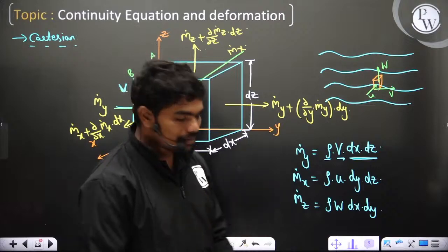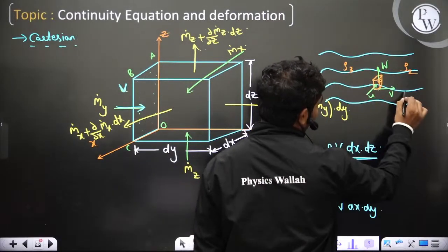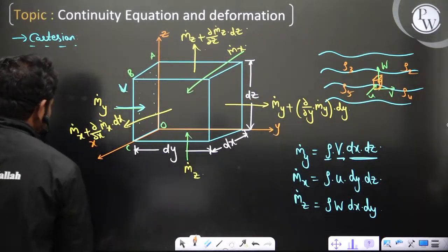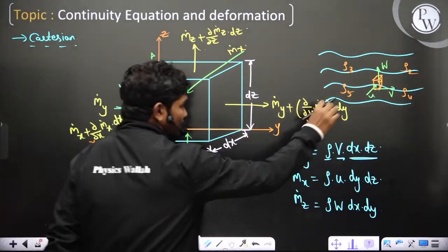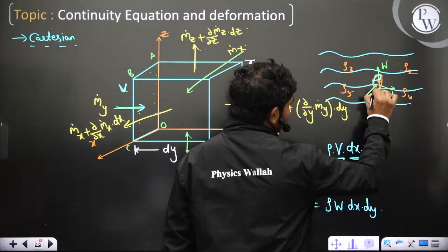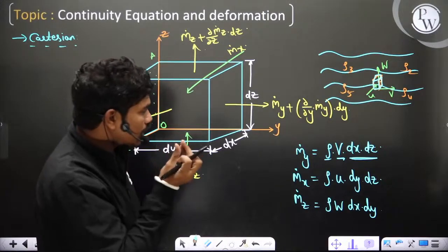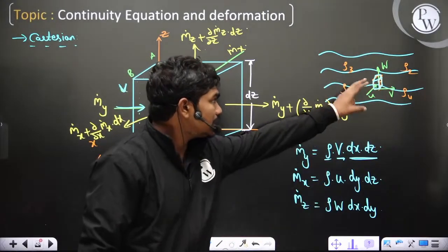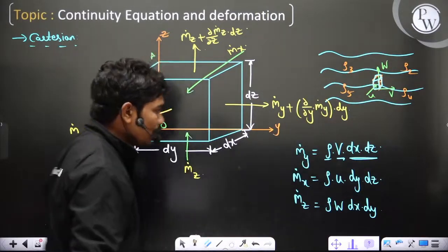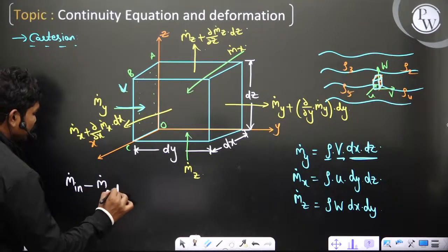Okay, now the main important point is this density may change from location to location, because the flow need not be incompressible. So it can change from location to location. Now you can see in this element, because practically this fluid element is of some fixed mass, if you take this small volume whatever you have here, then in that small elemental or differential volume whatever you take, this differential volume should be under mass conservation. Yes or no? Because the mass of the fluid element remains the same. So mass coming in minus mass coming out